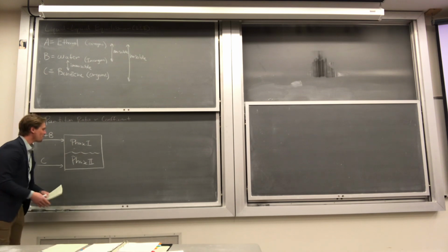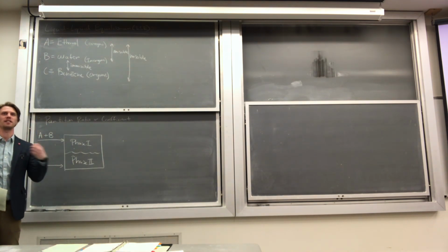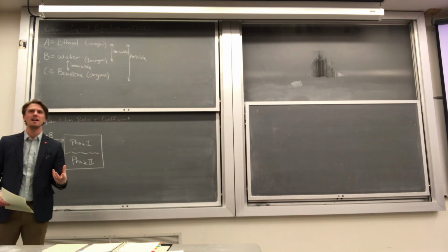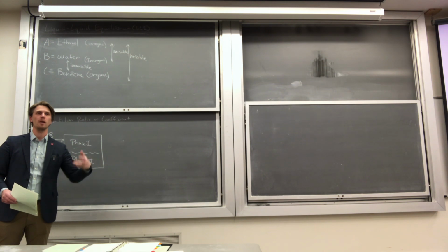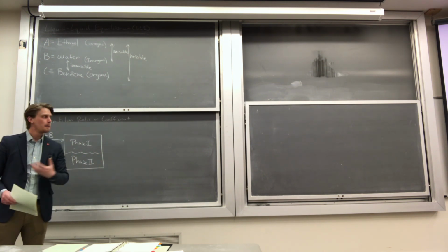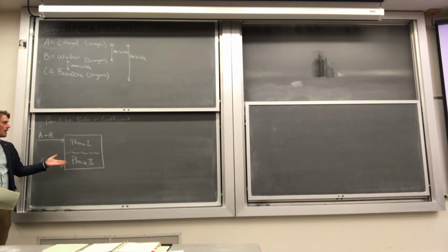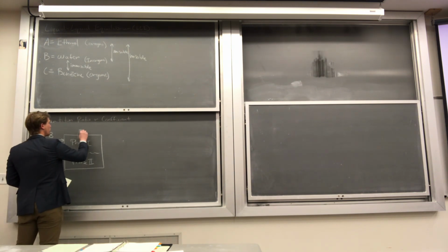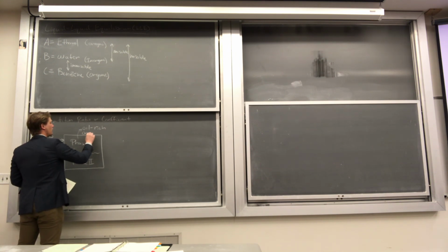Okay, so when we're talking about liquid-liquid equilibrium, we cannot say it's the vapor phase and the liquid phase, right? So Raoult's law is a phase equilibrium expression that relates between the properties of phase 1, vapor, and the properties of phase 2, liquid. In this case, when I have two liquid phases, I can call them phase 1 and phase 2. I can call this one, for example, oil-rich or organic-rich.